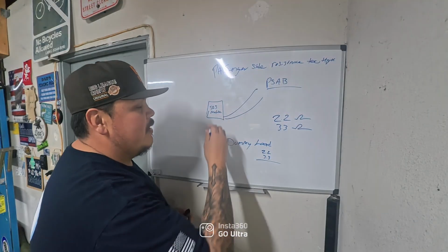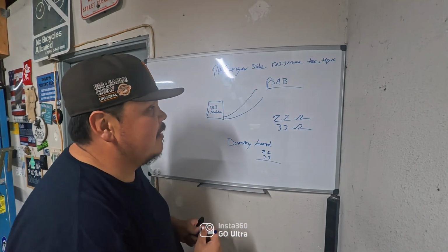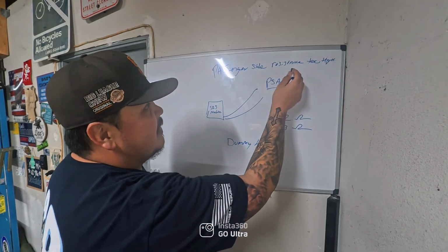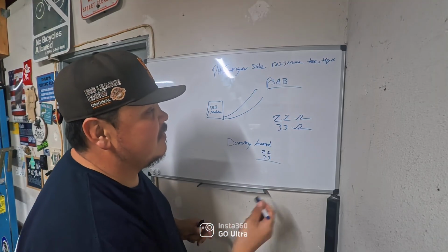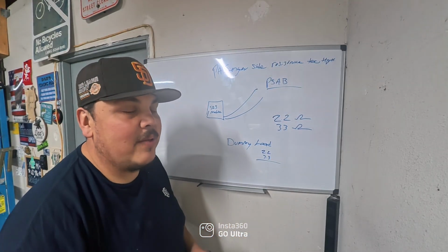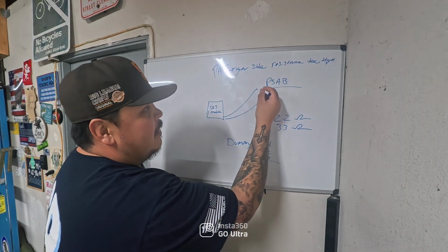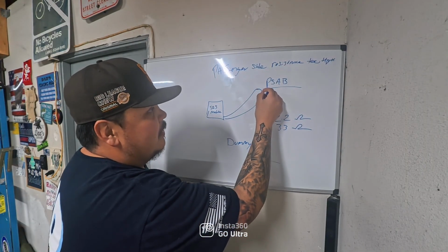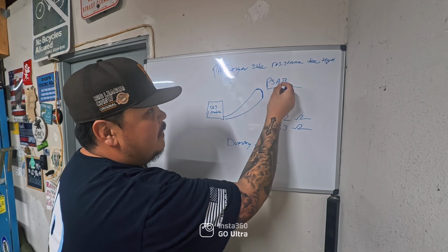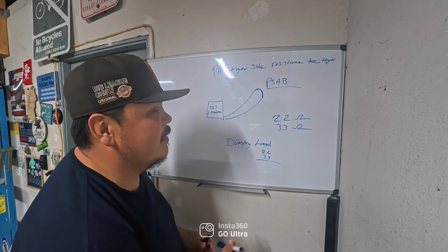Then you'll go to your SRS live data and compare the passenger side airbag resistance to the driver side. If it says 3.3, then you grab your 3.3 ohm dummy load, and you install the dummy load in place of the actual airbag.